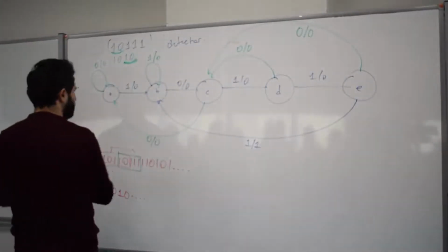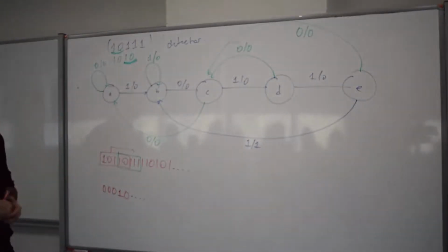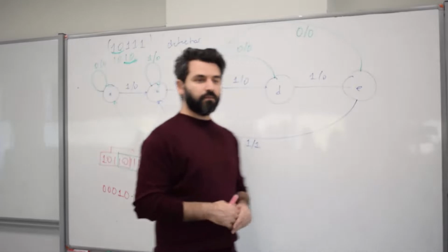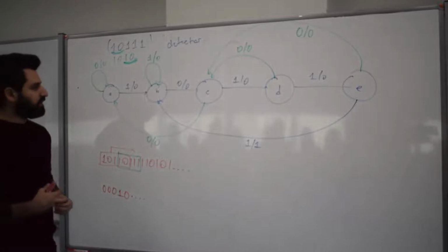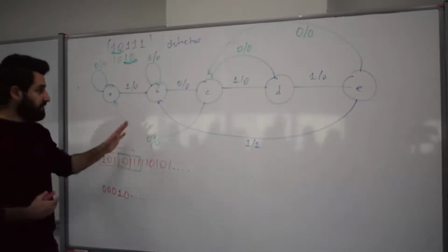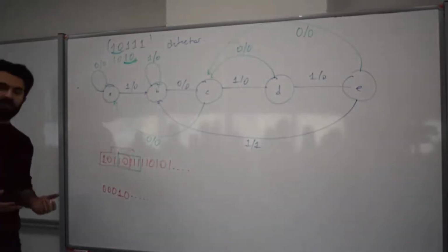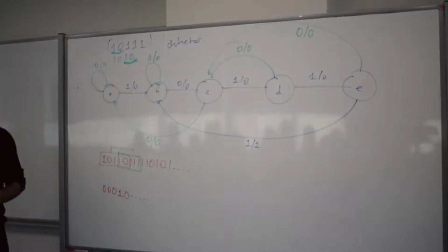You have to first make sure that your finite state machine works very well with another random input sequence. Then, of course, you have to go to the state table, by assigning all the possible input combinations of 1s and 0s, and then maybe state reduction, maybe that precedes that. What follows from that is going to be the Karnaugh maps, and then you draw the Karnaugh maps and make all these minimizations, optimizations to come up with the Boolean expressions, in other words, state equations. And finally, from the state equations, you draw the circuit diagram.